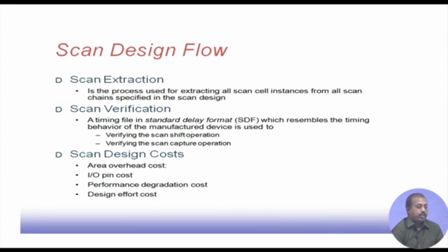Then there comes scan verification. A timing file in standard delay format, which resembles the timing behavior of the manufactured device, is used to verify the scan shift operation and scan capture operation, whether their delays are coming in proper timing or not. This standard delay format file has this timing information.